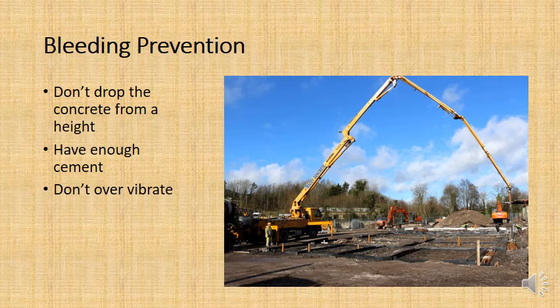It's for compacting the concrete, for pounding the concrete into the mold. Now, if you vibrate too deeply and the vibrator setting is too high, or you vibrate for too long, then you're going to start bleeding. That's a problem with vibrators. So you've got to use the vibrator wisely. If it starts to bleed, you take the vibrator out.